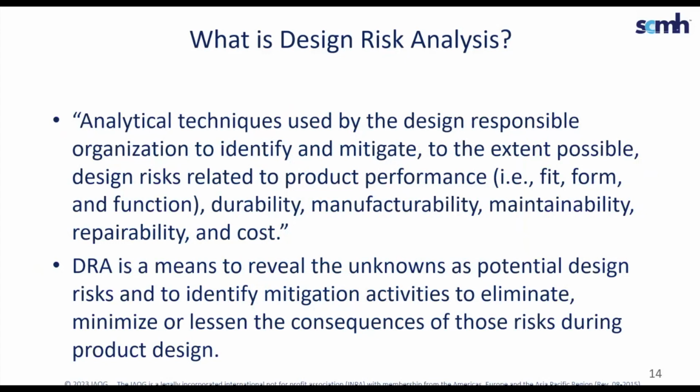You have functional hazard analysis, fault tree analysis, common mode analysis, etc., which are all tools within the safety assessment process. And any of those tools may be used to identify design risk. The safety assessment process will also inform the criticality of design risks identified throughout the DRA.